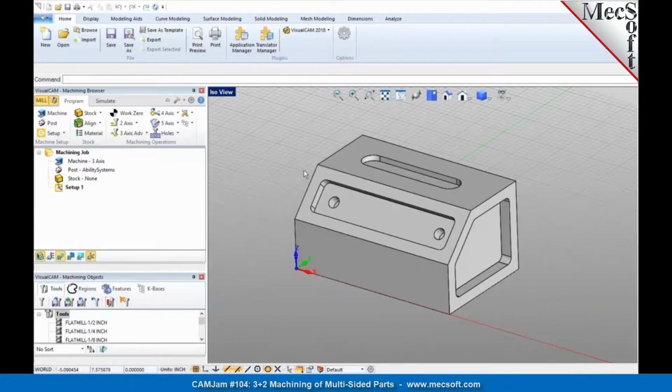So you would have to reorient the part or rotate the part in the host CAD system. In this case, in Visual CAD CAM and RhinoCam, you can rotate the part. If you're running Visual CAM for SOLIDWORKS or LibreCAM, we'll show you how we can orient the machine tool coordinate system to be able to machine from those orientations. So in Visual CAM and RhinoCam, you can orient the part so that the face that you would like to machine is parallel to the XY plane of the world coordinate system. So there are several different ways how we can do it.